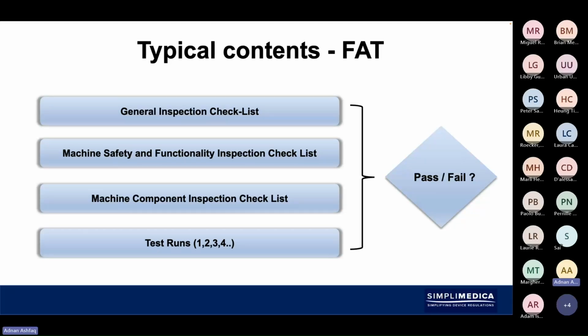You're going to have some situations where you might involve doing destructive testing. So the samples that you put through the equipment, you will never be able to recover again. So you have to factor in the costs of destroying product, which might be good product, it could be expensive product, but it's got to be an adequate amount that gives you the satisfaction that you are okay to now receive the equipment at your site. So only once we've achieved that satisfaction would we checklist off everything and say, right, we're good to go. You can now ship this to our site and we're ready to receive this.